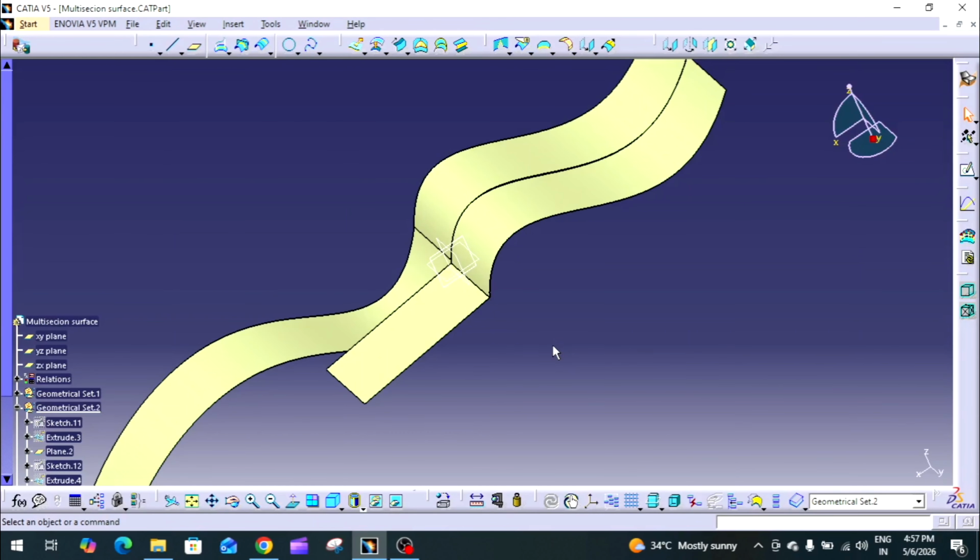You shall notice that gaps are closed, edges are merged, and the surfaces become cleaner and usable for further operations like join, trim, and solid creation. Always keep tolerance as low as possible to avoid distortion of geometry. Too high tolerance can alter your design unintentionally.